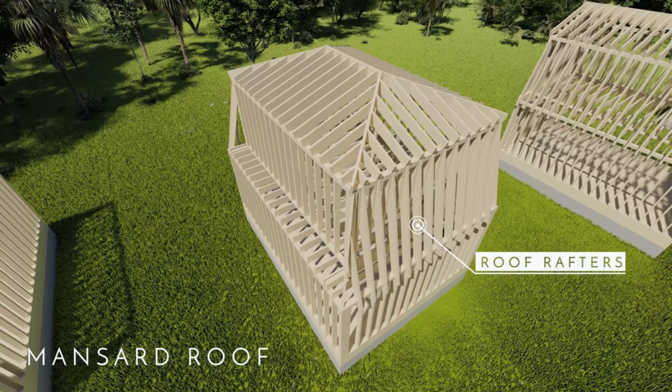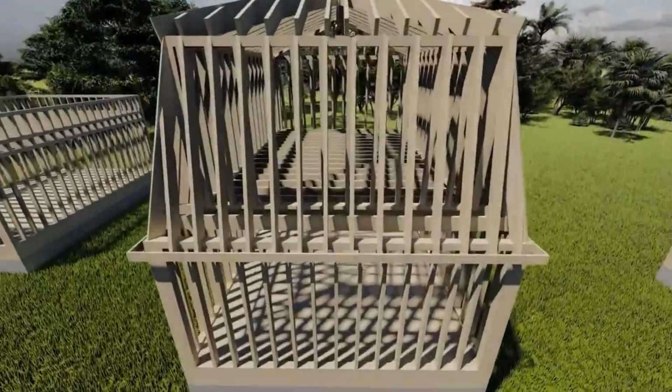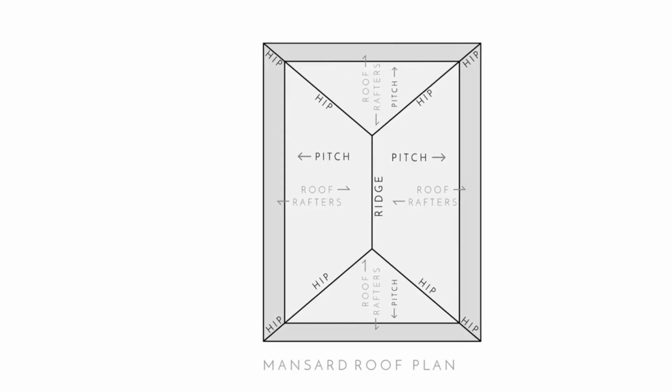Then everything in between the hip beams is filled with rafters, and the fascia board is there to cap off all of the rafters. So the mansard roof plan is very similar to the hip roof plan. The only difference is that the mansard has these offsets off of every side, and that's that steeper pitch that comes off each end. So we have the ridge in the middle, it doesn't quite go to each exterior wall, and in a mansard roof we have 8 hip beams, not 4. And then the roof rafters run from the highest point, and so does the pitch.